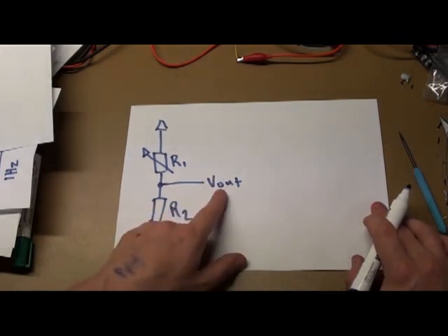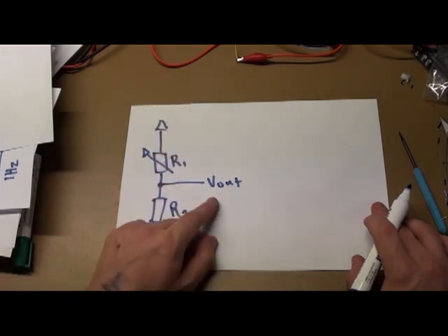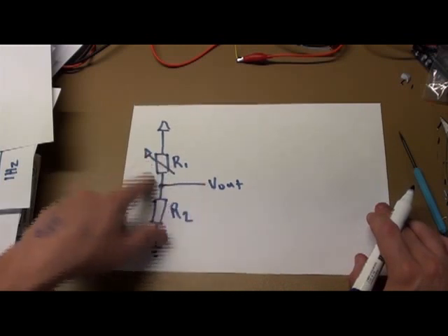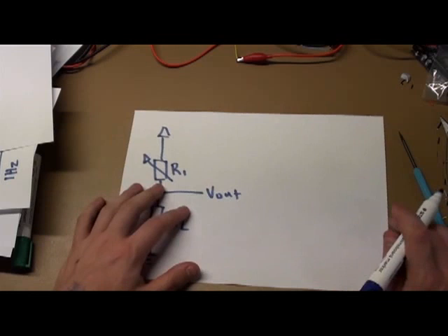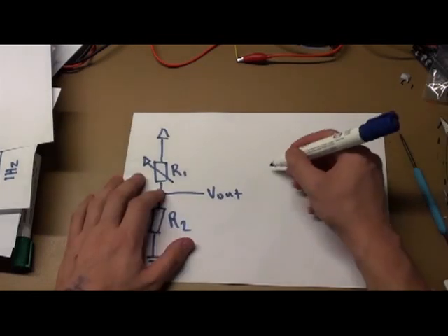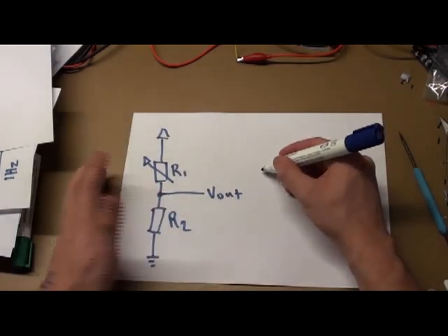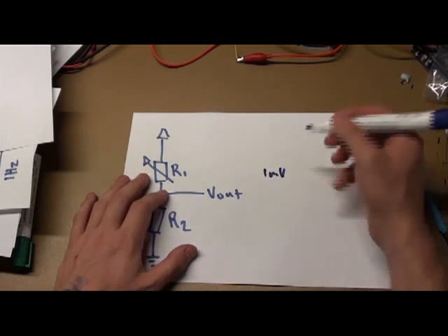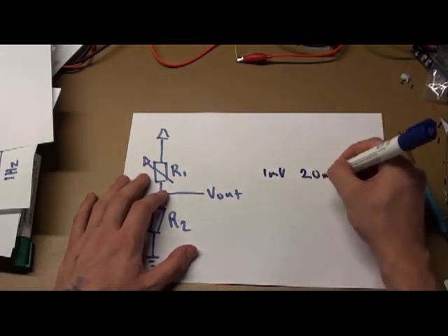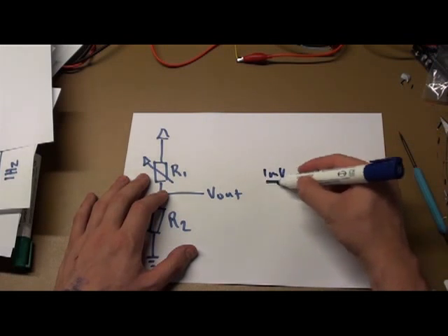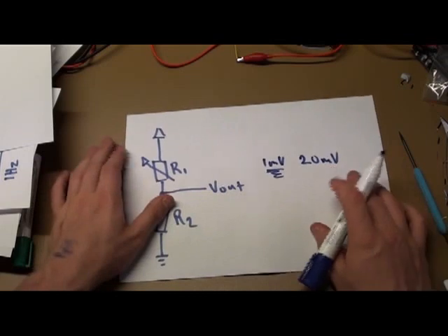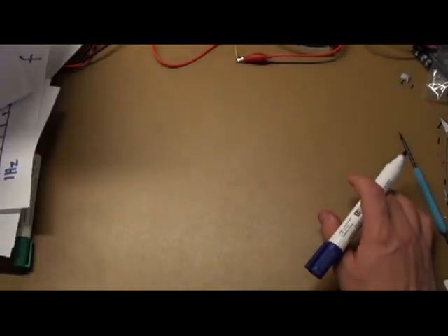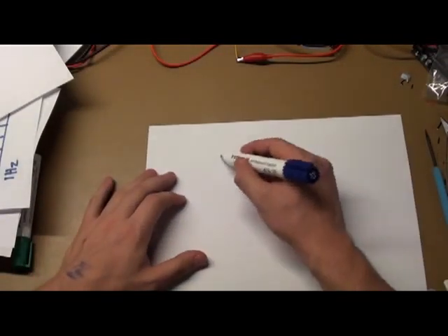And if you remember looking at the oscilloscope, the noise is, you know, it's small, but it's actually relative to a signal like that quite big. So really, all you'd get maybe, let's say, 1 millivolt. But if the noise is 20 millivolts, it's going to be kind of hard to find this one. So the way we solve this problem is by comparing it against a reference.